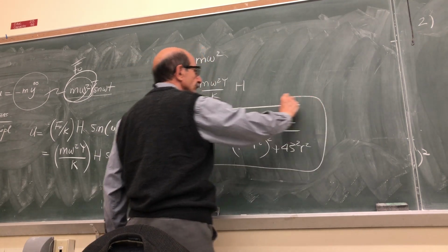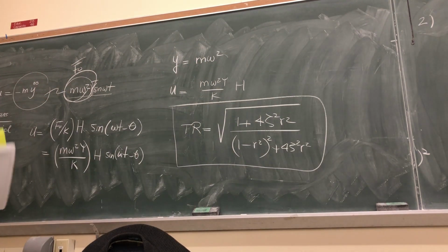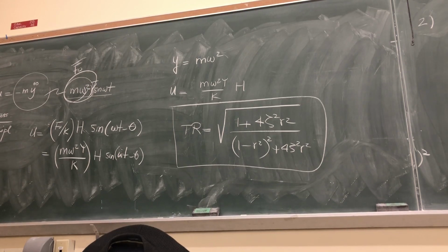So you end up with exactly the same expression. In other words, the transmissibility ratio function that you end up with would be exactly the same, identical to the case of the force transmitted in the system.